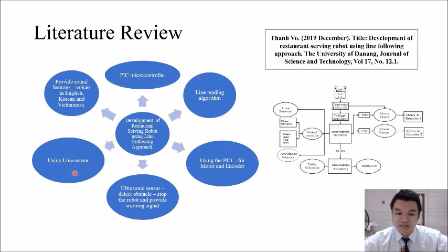combined with the line sensor, while also using PID for the motor and the encoder. They also use the ultrasonic sensor to detect obstacles, stop the robot and provide a warning signal. Lastly, they built sound features for the robot, which provide sound or voice in English, Korean, and Vietnamese. At the right-hand side of the slide is the block diagram proposed by them.